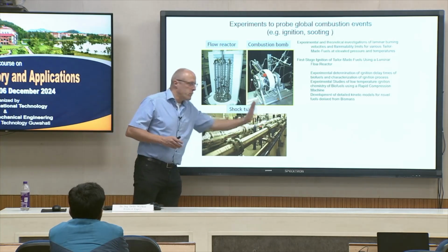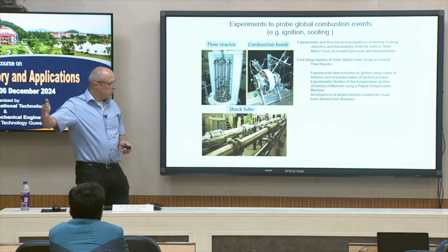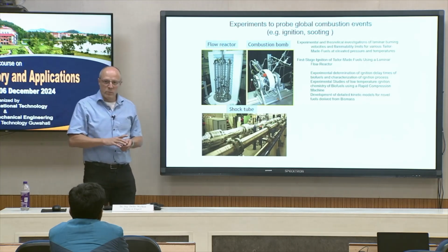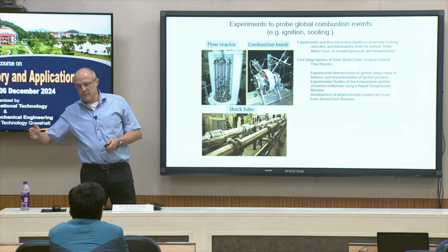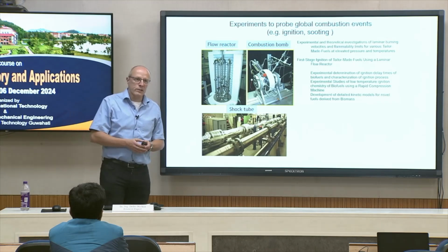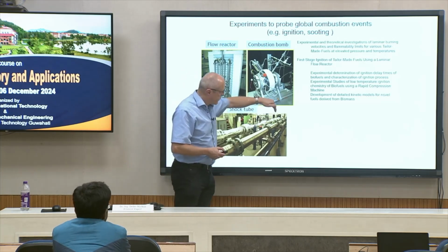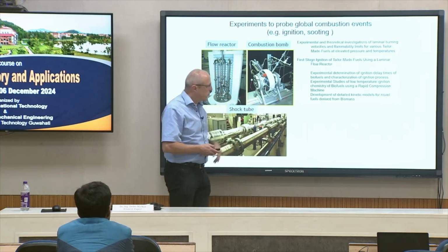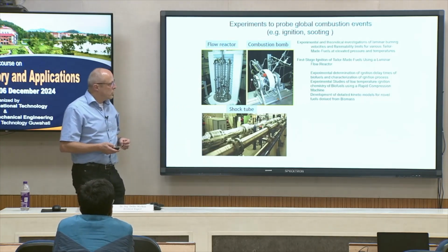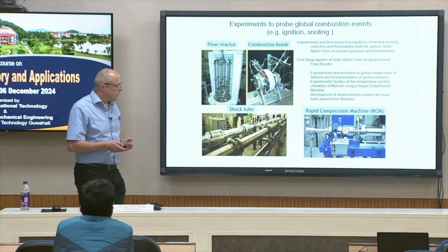Then we expand this high pressure in the driven part, and so we have a shock wave going through our system, heating up the unburned mixture. And normally we have this shock wave hitting the end wall and going back, heating up our system again. This compression wave, shock wave, then of course initiates our ignition process. And we know normally exactly the final temperature before ignition takes place.